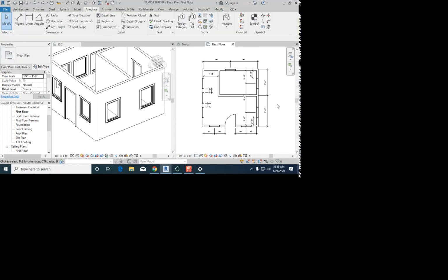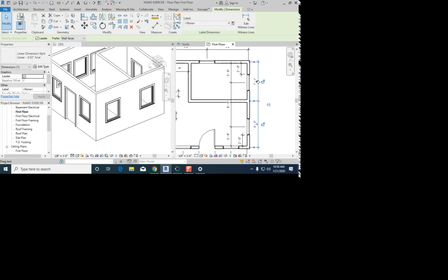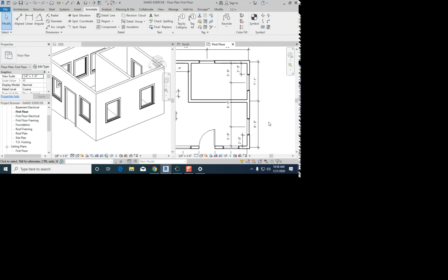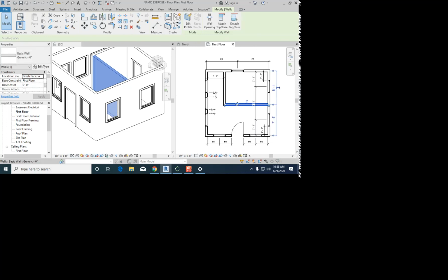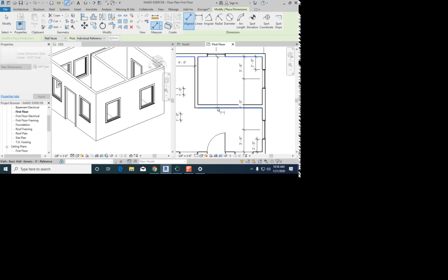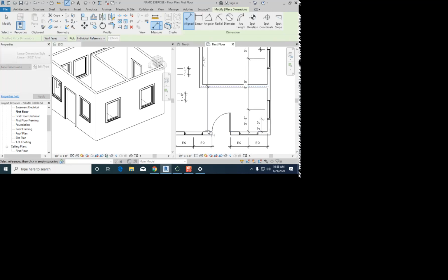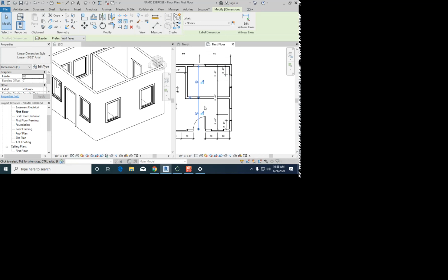Sure. So I clicked on my wall and I'm like, just place these dimensions. And then I click on the dimension and I click on equal. But like I said, there's more ways of doing this, so I can probably grab the wall. Nope, it's not telling me, hey, this is equal. I could also just not be lazy and put in my own dimensions, but this time I do want the center line. That's how I did it. You did? Okay, perfect, that works too. And then here, equal. Okay.